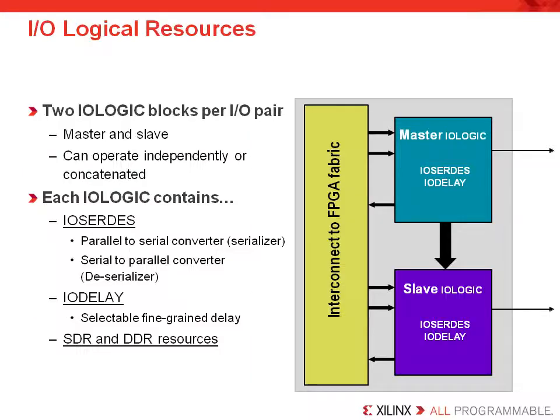Besides the register and SelectIO resources, there is also the SerDes functionality built into each IOB. This includes both parallel to serial and serial to parallel conversion. This is a programmable functionality that can decode a wide range of signals. The OSerDes/ISerDes combination is probably one of the most useful and radical developments.